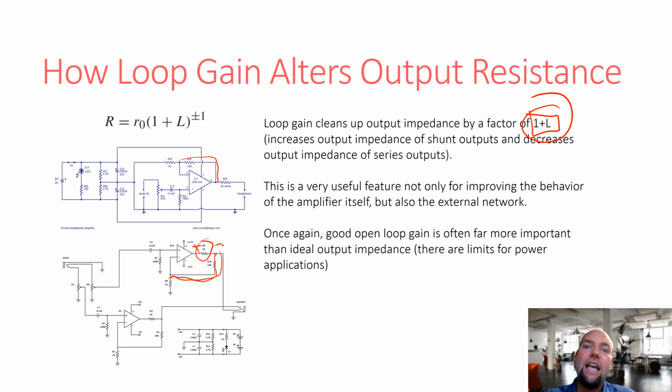So essentially, the op amp itself is going to have to output a bigger voltage in order to maintain the proper voltage at the output terminal. So what's going to happen is before this op amp gets to the point where it puts out too much current, it's going to rail. So basically, this output here is going to hit the rail of the op amp supply. And then once that happens, this signal on the other side of the resistor is going to clip.